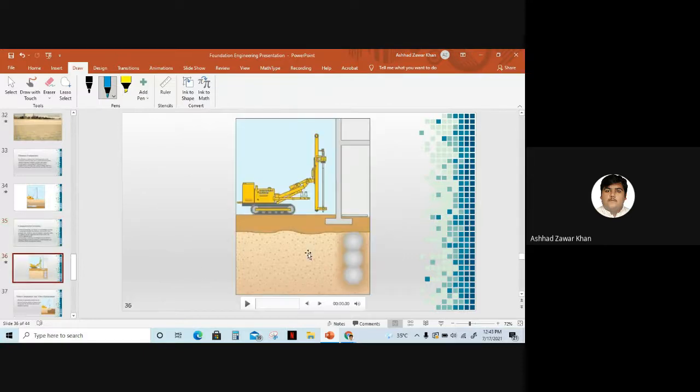This is like the previous one, but in this case, grout is injected inside the ground, like here, in the shape of balls, which quite improves the quality of the soil. This is compaction grouting, and this technique can be done in soil above which a structure is already built.